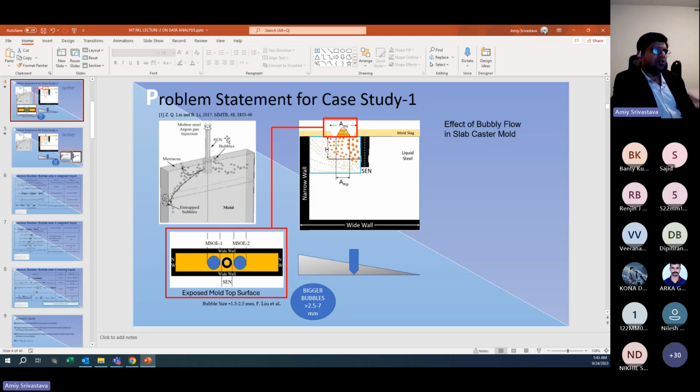You have to identify all those places. Also, if your nitrogen is very high and your customer allows you to add some titanium, titanium will help scavenge the nitrogen by making titanium nitride. But titanium nitride can be detrimental to the properties of the steel. For IF grade steel, how much titanium you are allowed to add, I don't know, so you can check that.